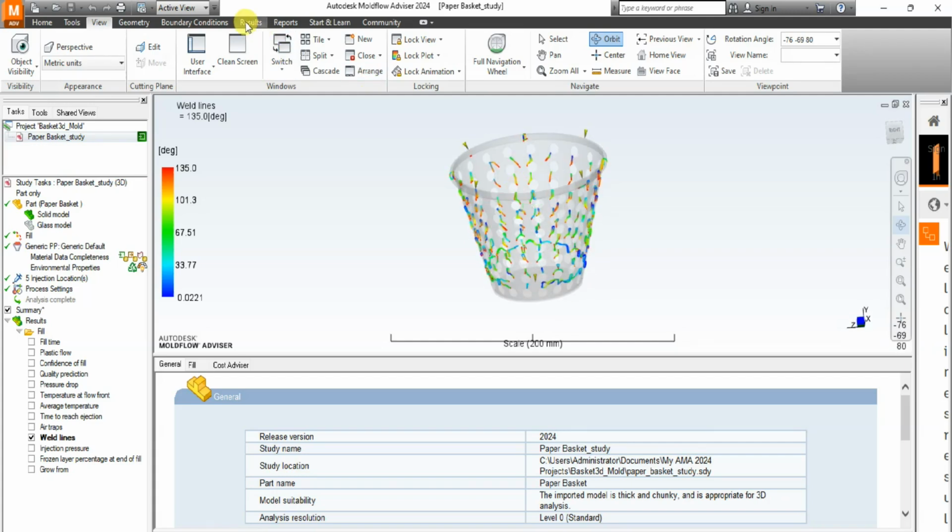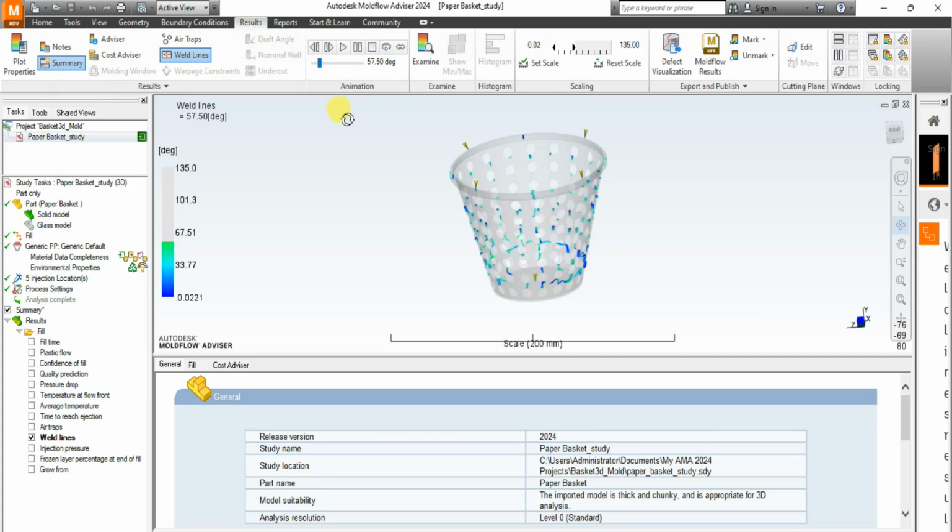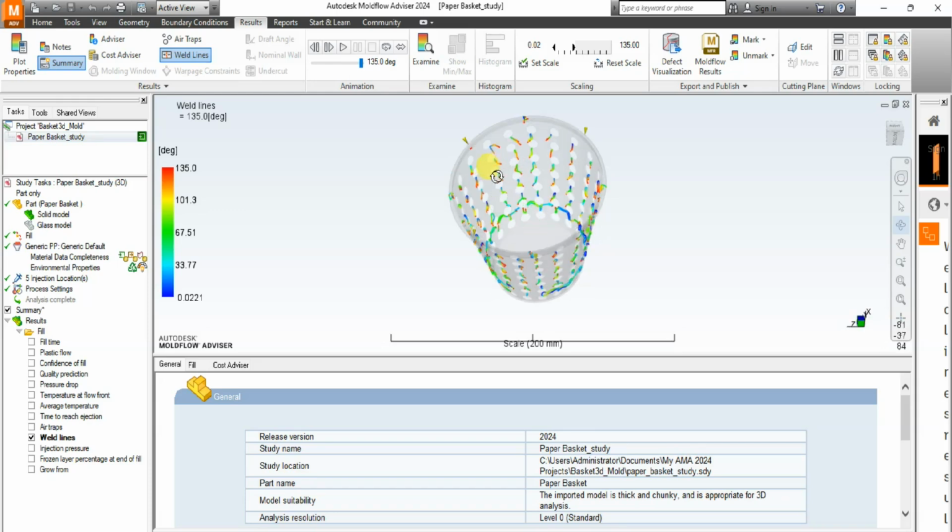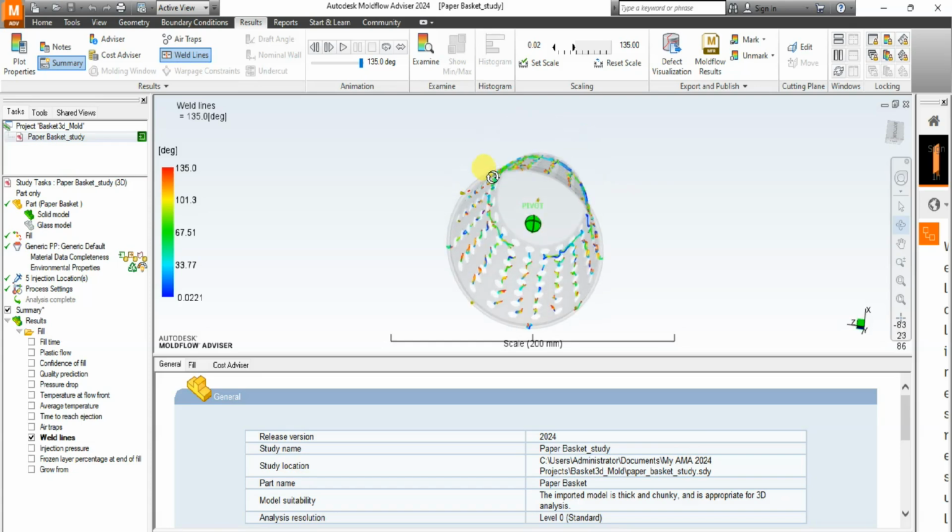The weld line is then created with higher flow front temperature and is packed with more pressure. So these things are of great importance. You can also place a vent in the area of the weld line. A vent is an airspace. This will remove the air traps, which would further weaken the weld line. You can also optimize the design of the runner system. Then you can reduce runner dimensions and maintain the same flow rate. Shear heating can then be utilized to increase the melt temperature at flow fronts.